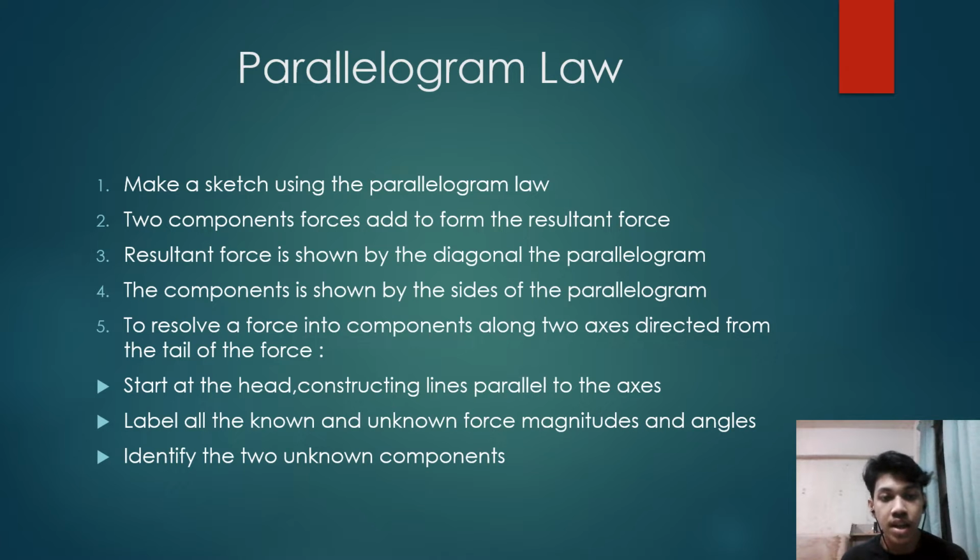We must start at the head by constructing lines parallel to the axes. Next, label all the known and unknown forces, magnitudes and angles. And the third one is to identify the two unknown components.